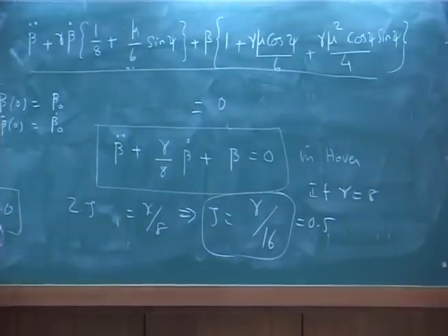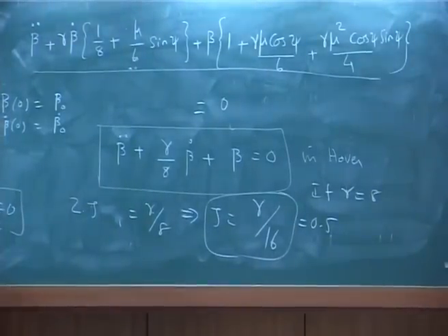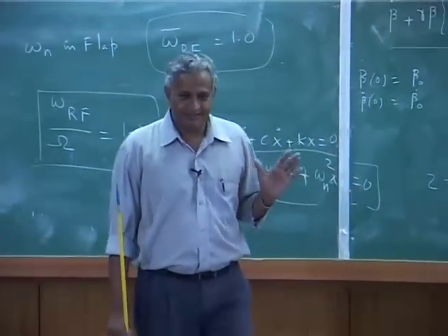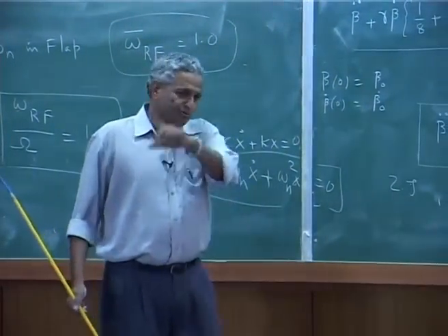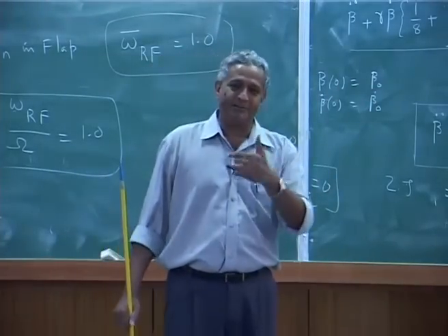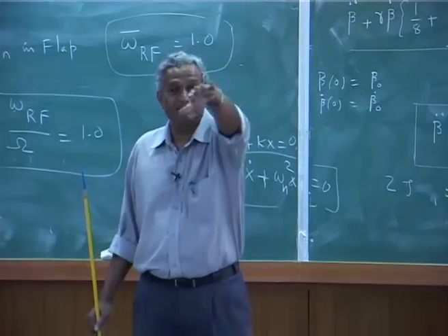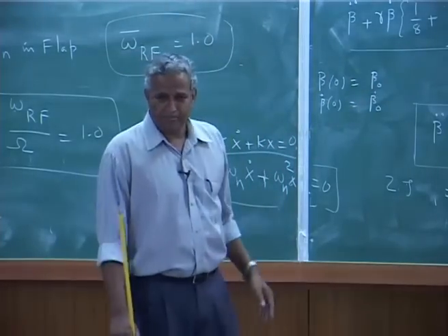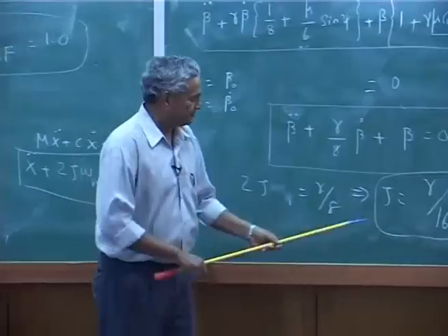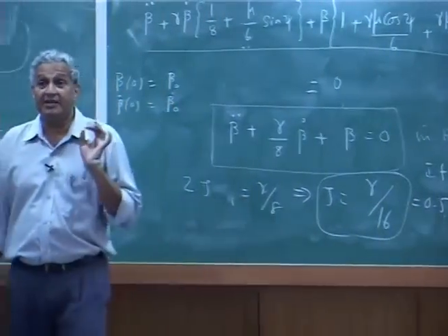It's high damping. Very high damping. So basically the flap motion is heavily damped, and it takes very short time to reach its steady state. Later we will calculate how much time it takes to reach its steady state value if there is a disturbance. That part we will analyze later. So with 0.5, flap motion is heavily damped.